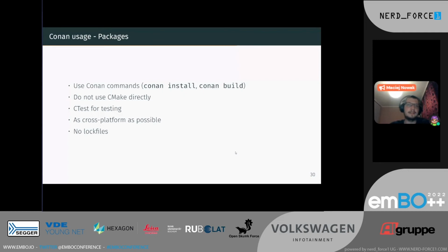But for unit tests built on the Cortex R5 platform, it's a bit harder because QEMU needs to be spun up to run the ELF file. With ctest, we have a consistent environment, and recently I even plugged in PyTest as a ctest unit test just to get a consistent interface.